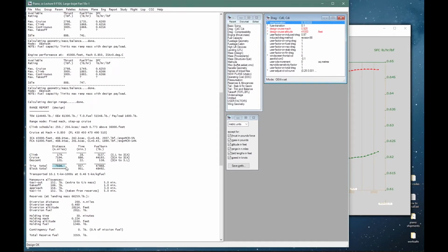Now, some level of uncertainty is always present. Even flight-tested performance numbers are themselves subject to significant interpretation. So fine-tuning the balance of assumptions like this can be argued differently between airframers and engine manufacturers, and that is a common situation. In previous lectures with the 787 and the A350, we applied direct user factors to match precise targets, for example in terms of the range. We can also fine-tune our assumptions like this to the extent that we feel confident about specific knowledge or experience from related airframes or engines.